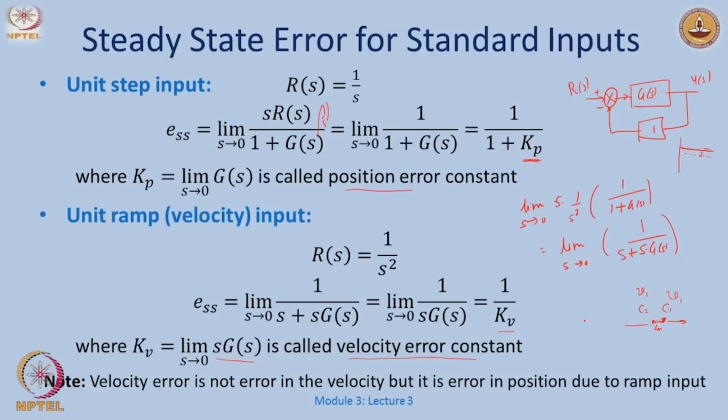Similarly, if I were to say, well, give me a temperature of 24 degrees, and I just go to 23, the steady state error here is 1, right. So, I am just tracking a position, I just want to go to 24. However, if I say keep on increasing my temperature profile with time in this way, okay, say it increases as 1 times T. This is my T and this is my temperature, the reference temperature, right, with time it just keeps on increasing.